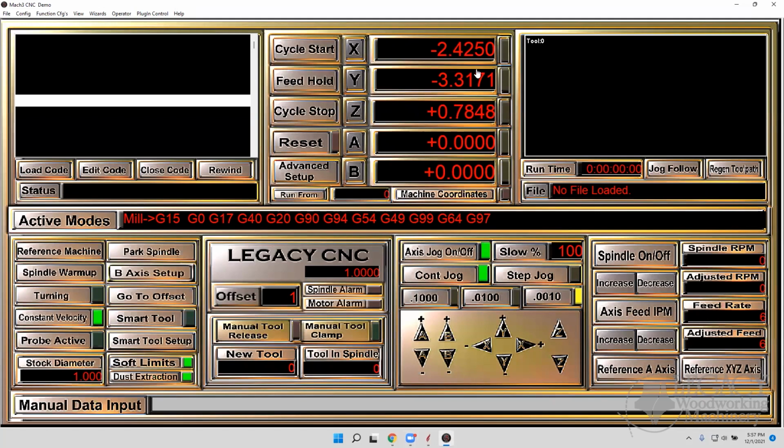And it's going to move to X0, Y0 right here. And that's 1/10 of 1/1000th of an inch and 2/10 of 1/1000th of an inch. So it's pretty accurate. Now let's say I just go to offset 3 and I hit enter. Then I just set X and Y. So now my number 3 and my number 1 are exactly the same.